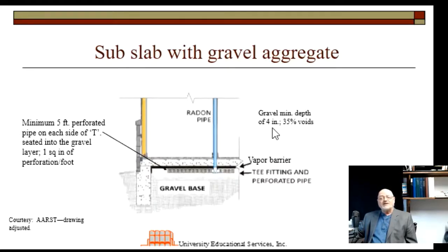It has to be at least 4 inches in depth, and I'll bet you're doing that already. And it must have 35% voids. And the standards tell you the size of stones that are used for that to accomplish 35% voids. And I'll bet you're doing that already. So you get the gravel base that you're going to have in here.